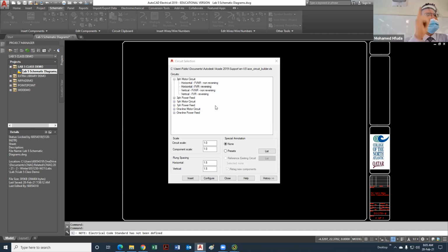Okay. Reduced voltage starting is particularly required or used for large size motors. Why are they required? Because without reduced voltage starting, the inrush current can affect other equipment, because when you're starting a large motor, it's going to pull very quickly on the system. If the system capacity is limited, it's going to reduce the voltage by more than 2.5%. See, this is the rule of thumb.